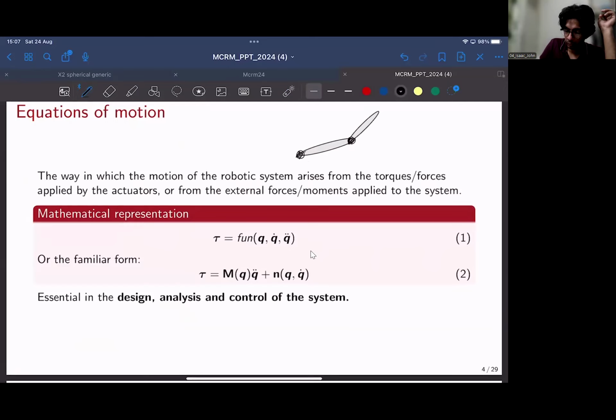If this robotic manipulator is subjected to forces at the end effector, for example, if the task of the manipulator is to pick a load from one position and place it on another, because of the physical weight of the payload, the end effector would be subjected to forces Fx, Fy, Fz, as well as the moments Mx, My, Mz.